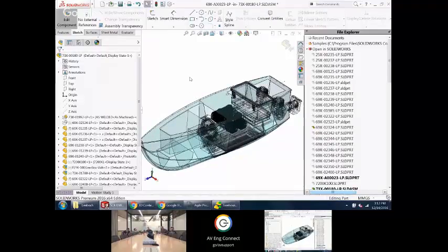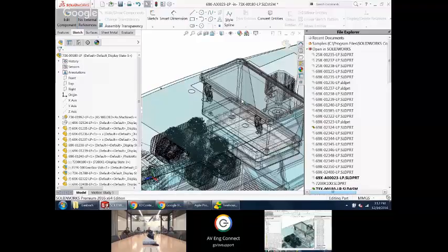Instead of me grabbing information and then going into the part later and stripping that out manually, there's this magic button right here called No External References. If you turn that on, you can still get geometrical information from an assembly. It just automatically breaks the link for you. So it does like a right-click, list external, break for you on the fly. I'll show you what that looks like here.